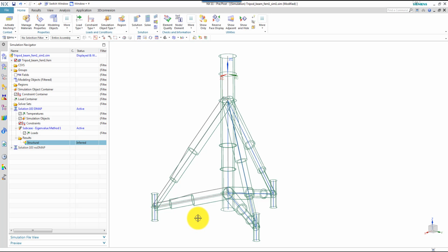However, the DMAP I've provided here will automatically set up the CSET as well. And the CSET is identical by default to the ASET. That means when you run the component mode synthesis, the CSET or ASET will also be kept fixed.